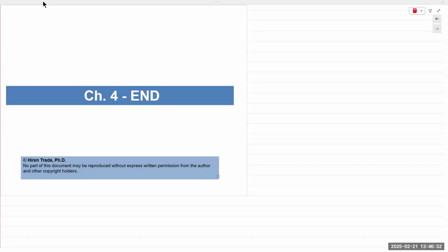And that would be 8. Actually, I have all of them here. All right, so 6 is basically we are taking different gates, creating a flip-flop, and then there is a separate IC which actually has a flip-flop, and we'll use that flip-flop to create a counter. Okay. So the first one, I believe, is using a NAND gate.